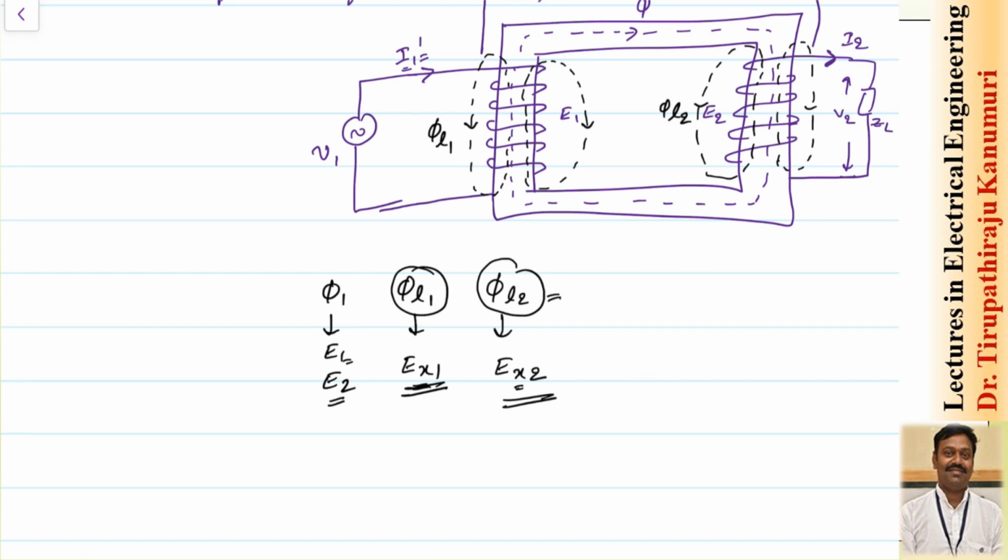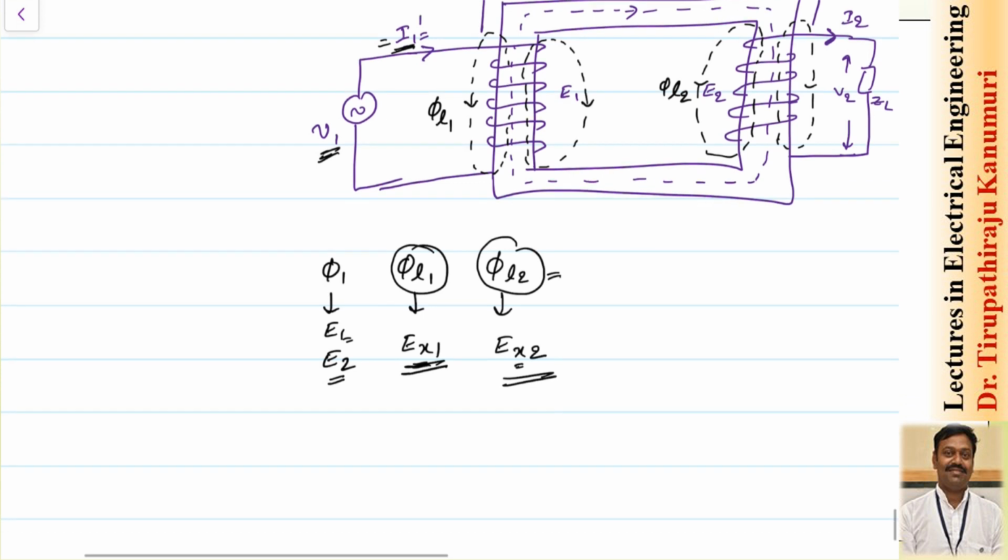one circuit to another circuit, because the major purpose of the transformer is that whatever the voltage and current is passing, V1 multiplied by I1 dash, should be transferred to the secondary, V2 multiplied by I2. But all the flux that is produced is not linking with the second winding, some flux is linking with the first winding only. So that is not responsible for the transfer of power from primary to secondary winding. Similar is the case for the flux linking in the secondary, that is not linking with the primary, or it is not responsible for any transfer of the energy.